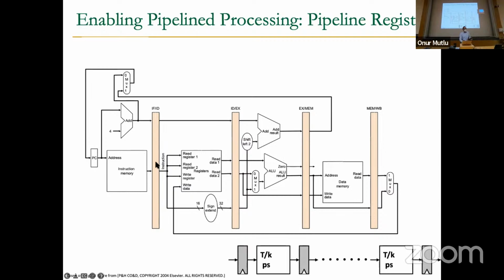And what is in these registers is of course the question, right? In this first cycle, here you're fetching one instruction. At the end of the cycle, you latch something, right? And then you of course have the program counter, which is a register as well that was already there anyway. So at the end of the cycle, you have the instruction register and PC+4 because you may need it later for branching or something else, exception handling, as we will see later on.